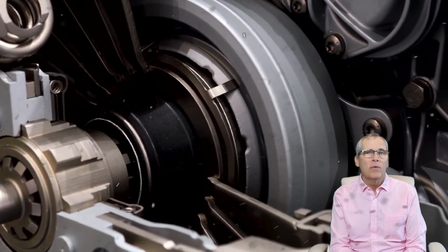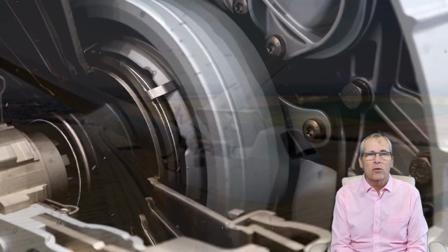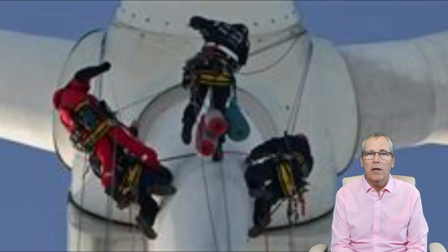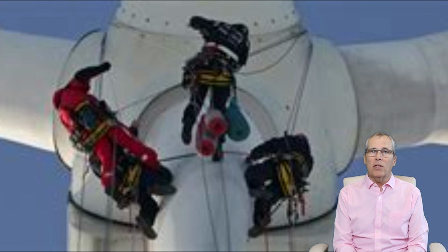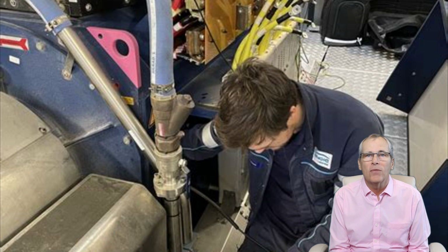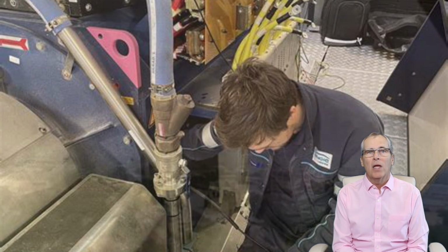To prevent wind turbine fires associated with obstructed air filters, it's important to have regular inspections and maintenance of the air filters, especially in areas with high dust conditions. This can help ensure that the air filters are working correctly and any issues are caught and addressed before they can lead to a fire. It's also important to monitor the wind conditions and dust levels to make adjustments to the wind turbine's operations as needed to minimize the risk of obstructed air filters.